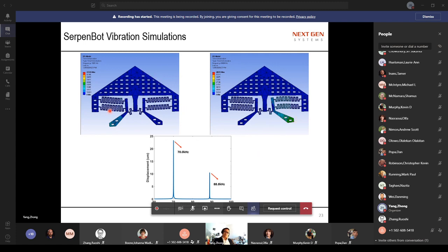This vibration analysis shows us that this actuator has two peaks, similar to our analytical analysis. The problem is that the values are a little different from our analytical model, because the boundary conditions have some differences and also some uncertainty.